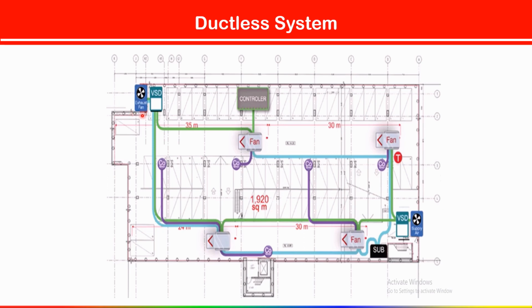Here we have an exhaust fan, and here we have a supply air fan, meaning a fresh air fan, to supply air into the basement. We use the exhaust fan to exhaust the air from the basement. Here we have installed an axial fan, or a centrifugal fan if you are using that. Some distance is maintained from fan to fan. How much? Somewhere we use a 30-meter distance.